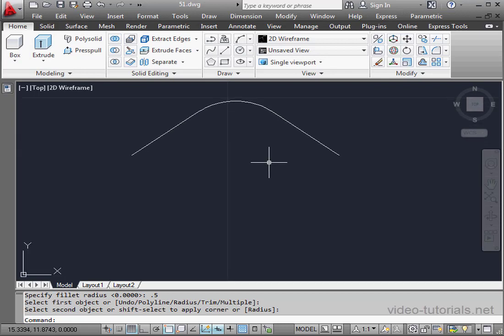Let's see how we can improve the smoothness of this transition. The greatest level of continuity we can achieve between an arc and a line is G1, or tangent continuity. That's where the arc and the line share a coincident point and a tangent constraint has been applied. However, if we replace our straight line with a spline, we get more options. Let's copy our geometry.